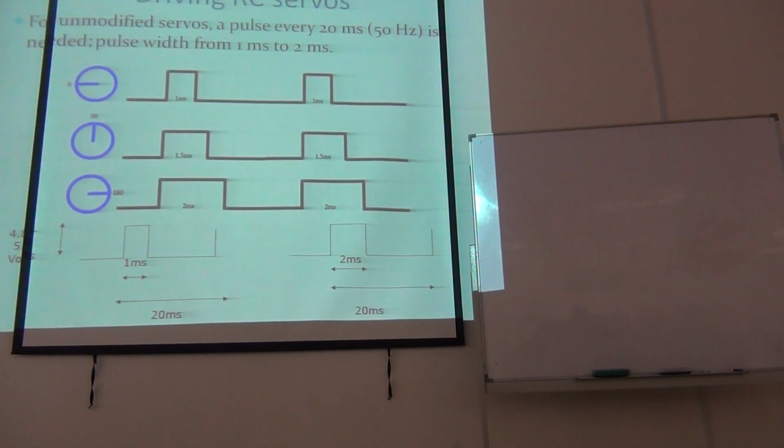Okay, so very simple. If you have this type of PWM, 1 millisecond for the PWM, the whole period must be 20 milliseconds. For the servo motor, the total period from here to here is 20 milliseconds only, which the CCP pins cannot support. So if this PWM is 1 millisecond and the rest is 19 milliseconds down, and keeps on repeating, your servo motor will be controlled to 0 degree. Servo motor will move to 0 degree.